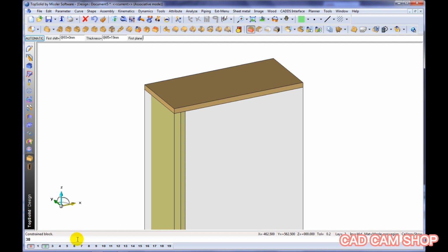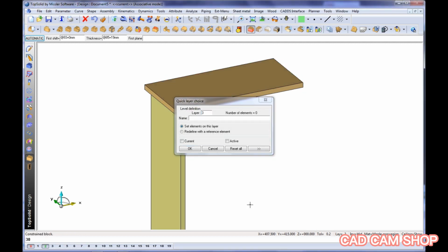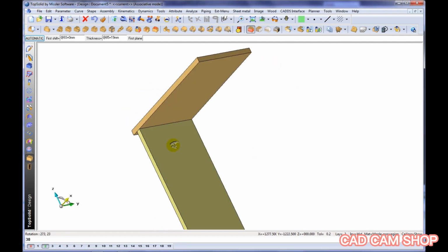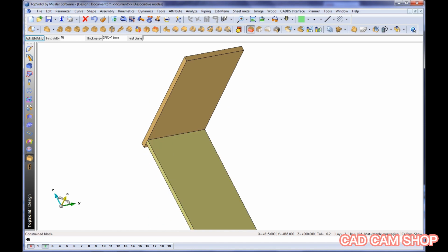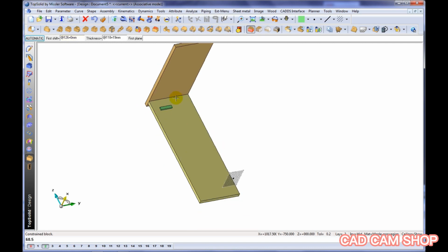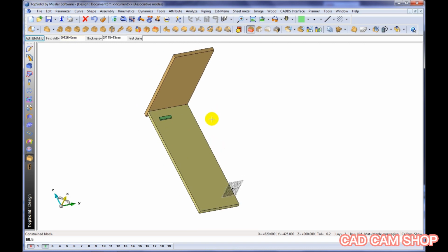Next, we're going to go to a different layer, and we're going to draw yet another piece. It's going to start off that face and shift from this back face forward, and it's then going to extrude forward for maybe 8 millimeters. And then we'll locate it off this face and shift that down for half as well. Perfect.